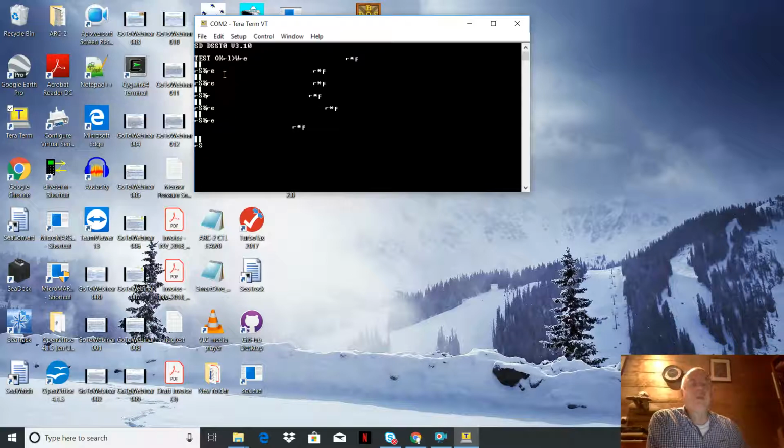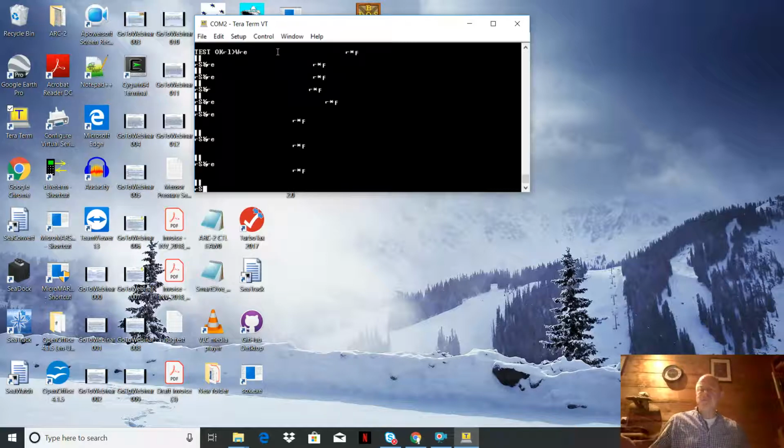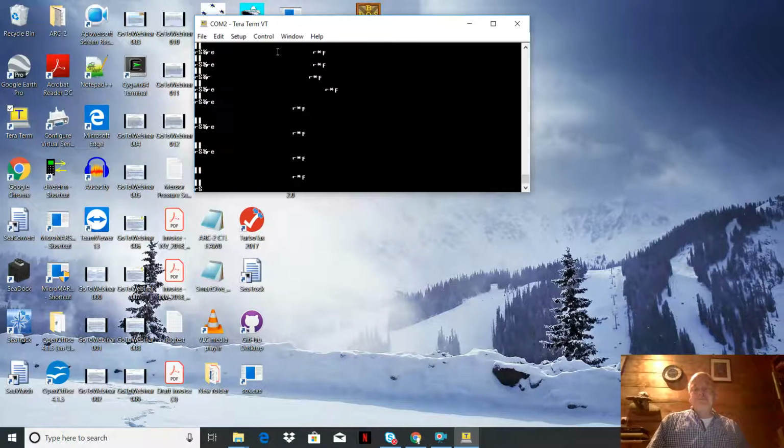There are some test results that can be sporadic, but that is also not anything to worry about until it becomes very persistent, and then maybe you want to call Desert Star Systems and let them know what you found here. So here at least I can see, all right, the STM3 is talking to my PC. There's no doubt about it. So if I still have a problem with the ARC control, then really there's probably some issue with the PC, a firewall, or whatever it might be. I'd have an IT guy look into it.